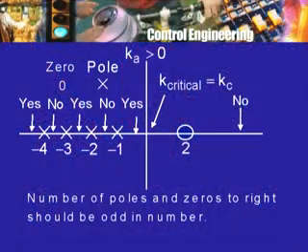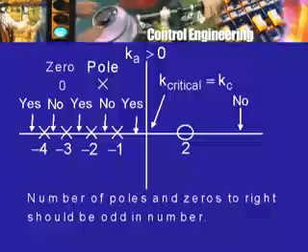However, that particular rule that I mentioned, namely a point on the real axis belongs to the root locus under such and such condition, can be obtained more simply without using the angle condition, and it goes like this. I am mentioning this because you should know various alternative ways of getting at results. So here was our example. We had some poles at minus 1, minus 3, minus 4, two zeros, 2 and minus 2, and we are trying to determine whether a given point is on the root locus or not.